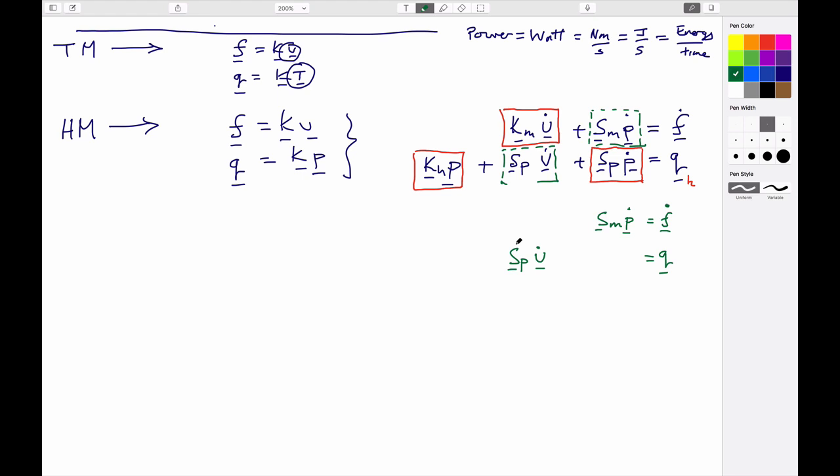We're going to compress it at some rate, and it's going to get smaller. And if the pressure doesn't change, because it's squeezing, the only way that pressure can't change is if it's allowing the fluid to squeeze out of it. And so basically this is a relationship that's saying we're compressing this at some volumetric compression rate, and the amount of fluid that comes out of it is exactly equal to that volumetric compression rate.